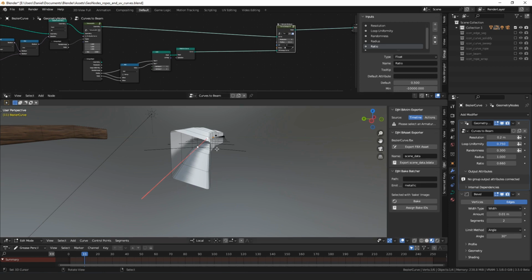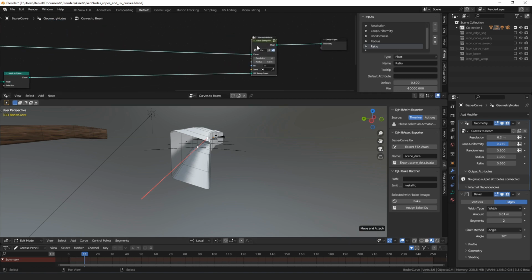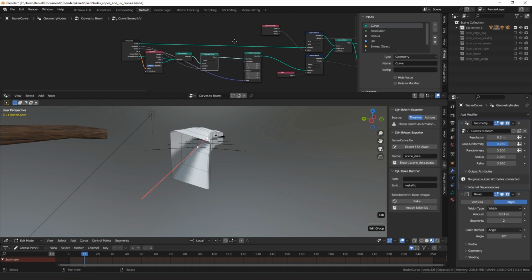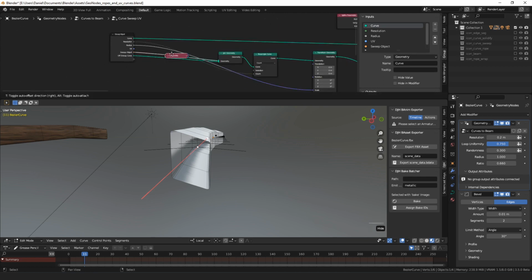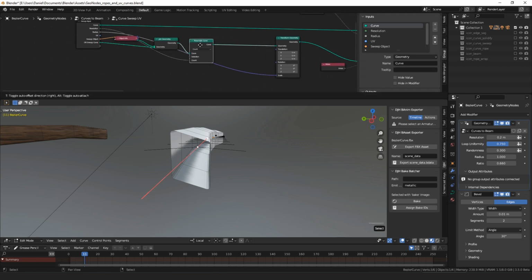And it's doing that because it's resampling the curve, which I hadn't considered. So let's quickly modify the curve sweep node so that there's an option to resample or not. So we can see here in the curve sweep node, you can either connect a curve object or do a swept curve, and then those are both resampled.